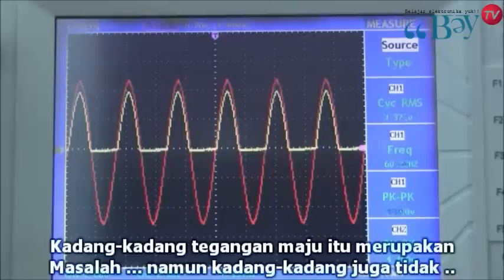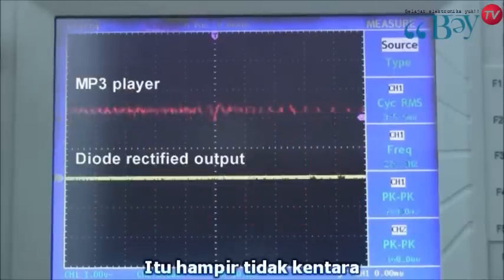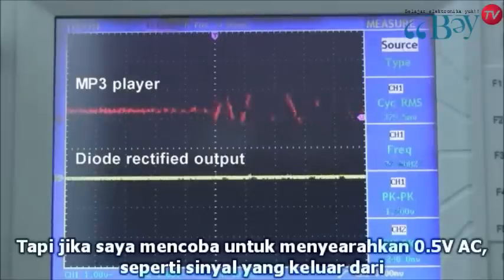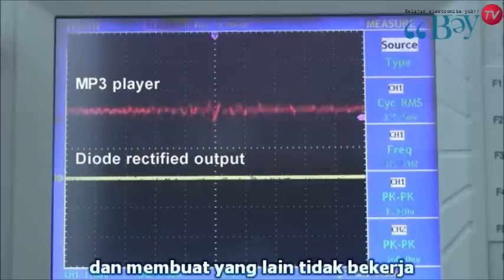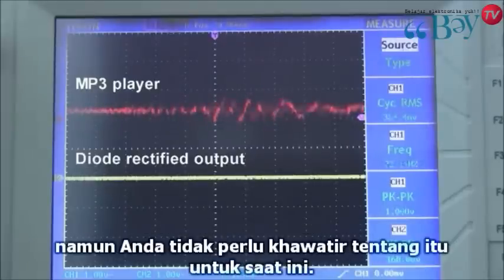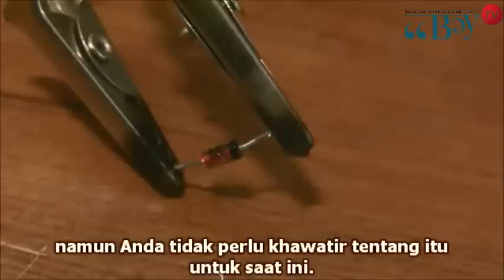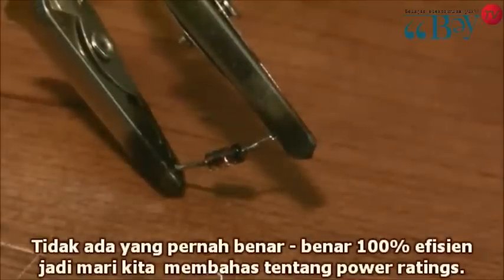Now, sometimes that forward voltage is a problem, sometimes it's not. For the example I was showing you here with the 10 volts peak-to-peak on the input, it was almost unnoticeable. But if I was trying to rectify half a volt AC, like the signal coming out of my MP3 player, that 0.7 volt drop becomes really annoying and it doesn't really work. You'll have to use advanced techniques like superdiodes to deal with it, but you don't need to worry about that for now. Now, nothing is ever 100% efficient, so let's talk about power ratings.